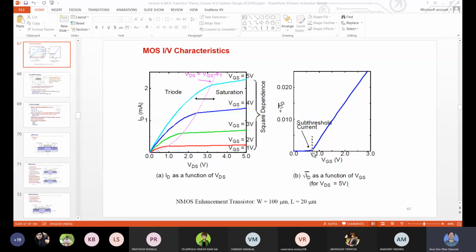In that case, in short channel devices, still some electrons are reaching below the oxide. So below the oxide, still a smaller number of electrons are reaching. Their density is not exactly the same as that in the bulk of the semiconductor. In the bulk of the substrate, it is hole density. It is not equal to that much, but it is there. Some means a smaller number is there. So whatever inversion is happening, that is called weak inversion.